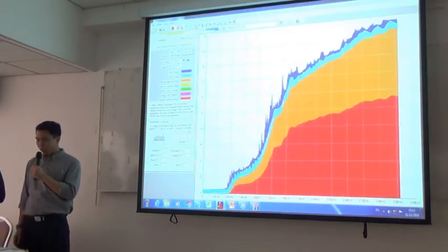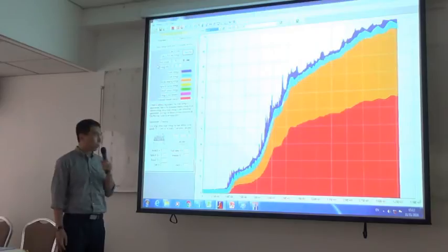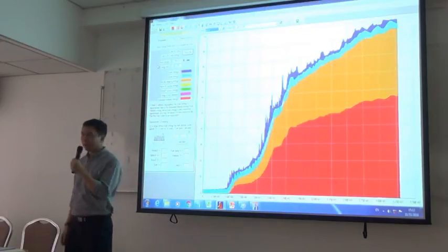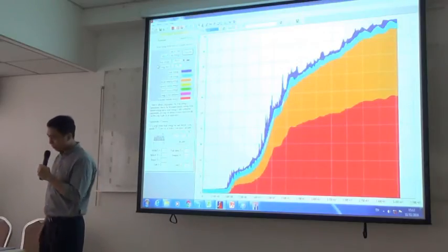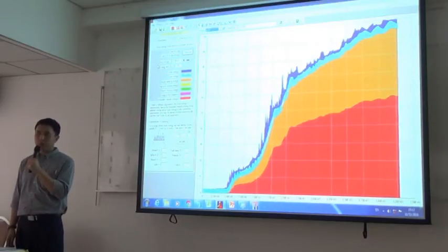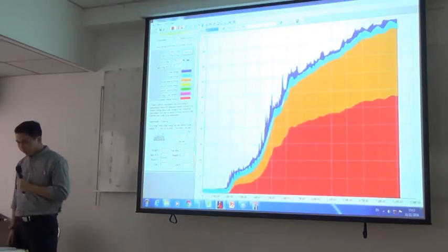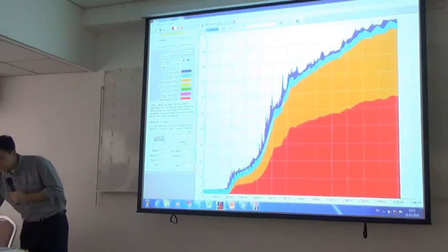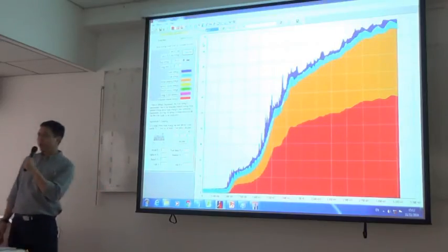First, we have to check the energy error percentage. Here, the energy error percentage is 1.19%, which is in the acceptable range. If the energy error is more than 5%, we have to recheck the model and fix it, and then rerun the analysis. Now the energy error is okay. That energy error is the difference between input and output energy.